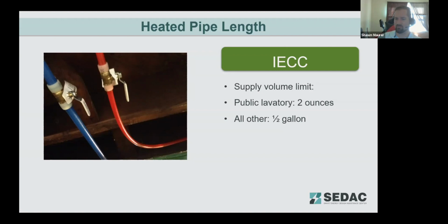With newer half-gallon per minute faucet aerators, that flow rate is only about 1 ounce per second. So with the seemingly minute 2 ounce allotment, that's still 2 seconds from when the tap is turned on before hot water arrives, which may not seem like a long time unless you're standing there waiting for it. So here the ASHRAE is taking into consideration how much cold, stagnant water is in that hot water line. It has to be passed out before hot water reaches that service faucet.